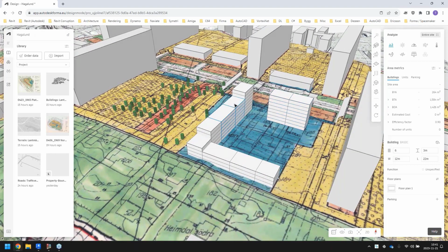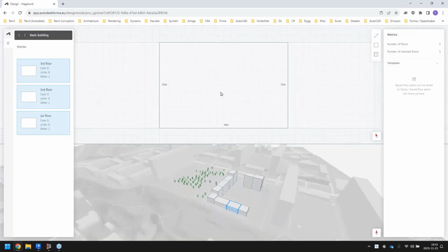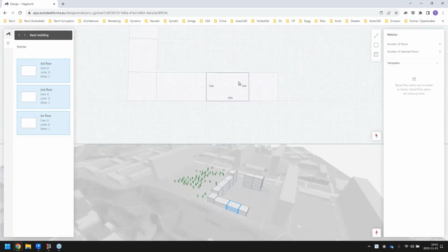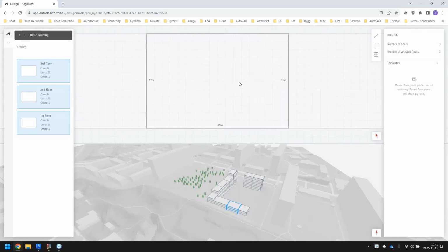And something that's pretty new in Forma is that you can actually go into these now and specify the floor plans of them. So if you click one of these and you go here on floor plans, just click floor plan, and you come into some kind of simple paint program, or, well, I shouldn't say AutoCAD program, but a simple CAD program. And using lines, you can just divide this one into the different areas where you think you will have apartments. So I'm just using the shortcut for line, which is here.